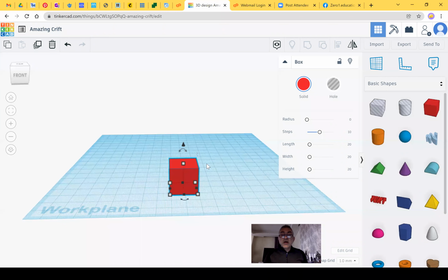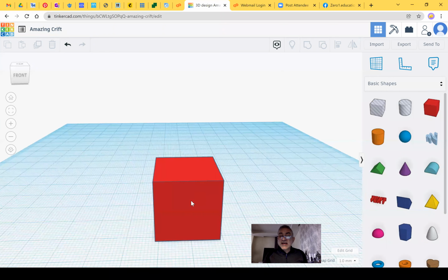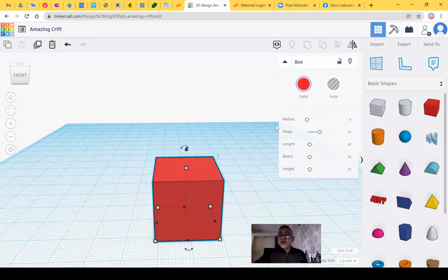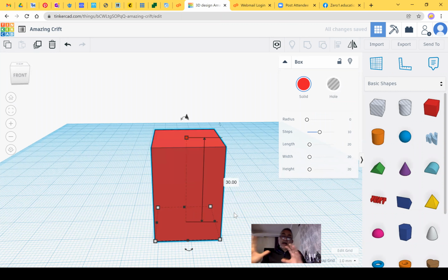But even if you click on the cube without modifying the values here, by clicking on any of the points all around the object, by clicking once, you can directly select and change the value from here. So it's a second way of modifying the properties of the cube.